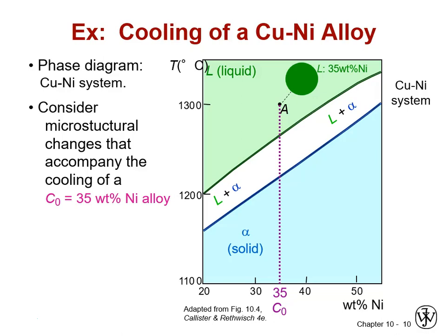We're familiar with the idea that we have grains, and if we have another phase, it'll probably want to precipitate on a grain boundary, and it'll form its own grain, and it'll probably have its own crystal structure. Some will be FCC and BCC, and we can get different things dissolved in each one of them in the interstitial positions or as solid solution substitutions. For instance, our copper nickel is definitely a substitutional solid solution. It's not interstitial.